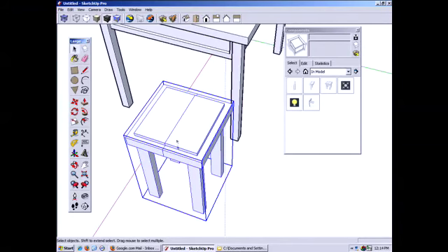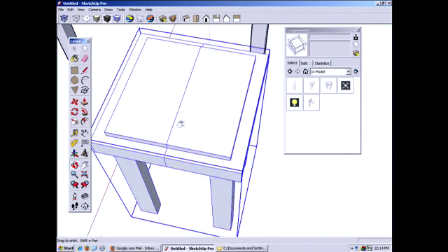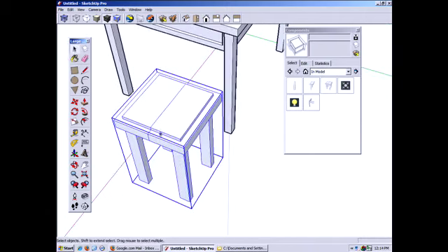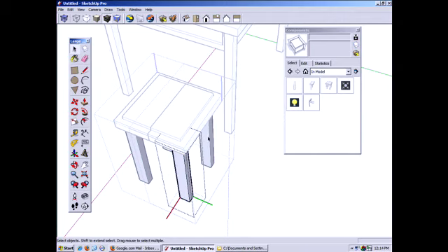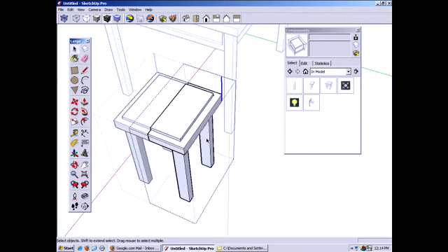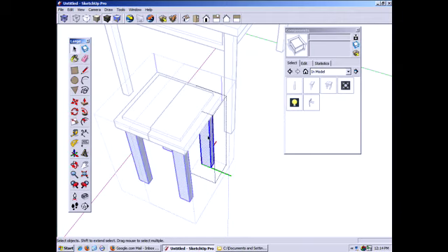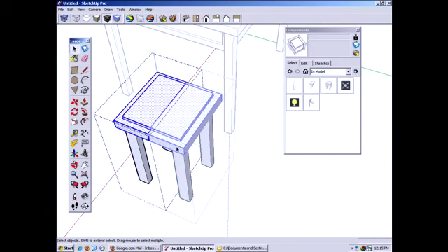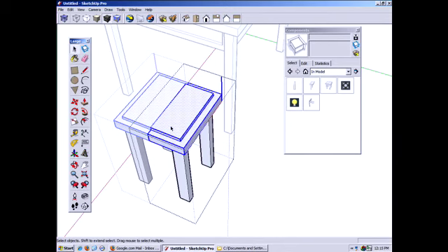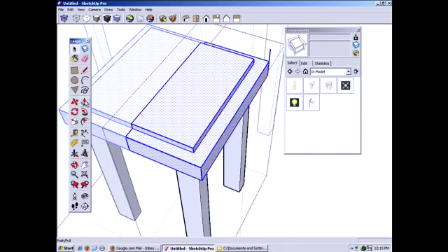So we still have this larger component. Let's use this paste in place to our advantage again. Let's come back here, and actually let's double click a couple times. When I'm editing components at various levels, I sometimes get double click happy because that just sort of works. You're like, all right, whoa, where was I? And you just sort of double click until you find the native geometry that you're trying to find. That oftentimes works for me. So I double click until I find this. Okay, that's what I want to edit.